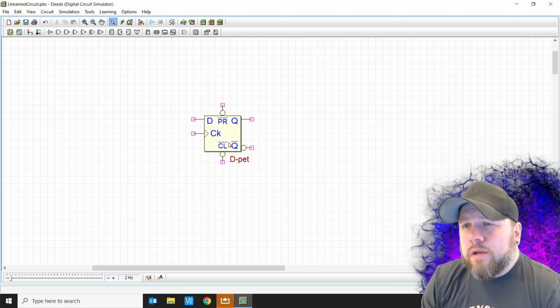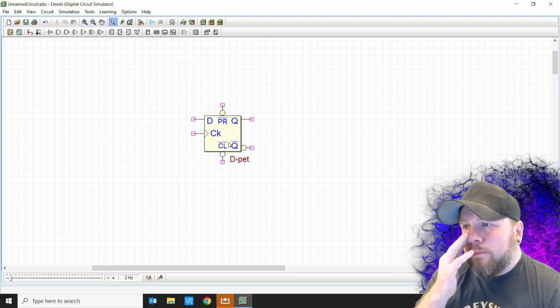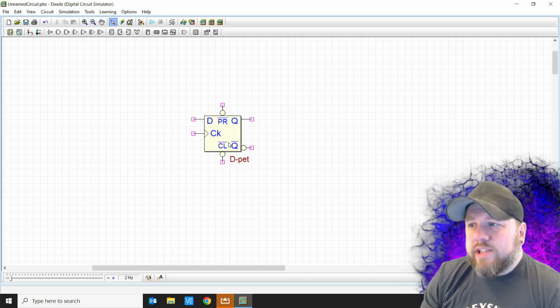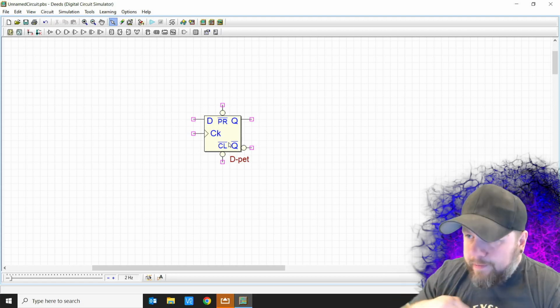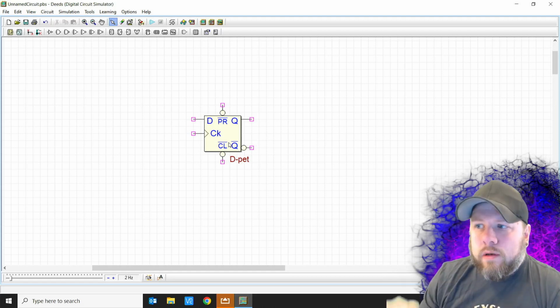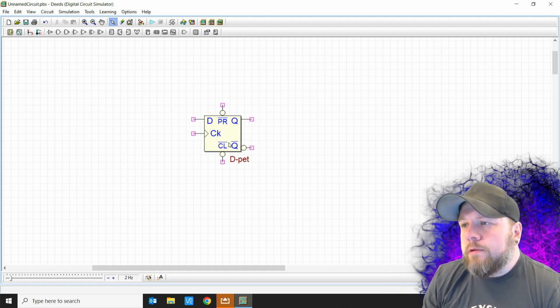Sometimes it's by nature of what the design is that you might have 32 outputs and only one of them would be low. So as opposed to saying all of them are on and then that low one being off, we can flip the script and say that it's active low.